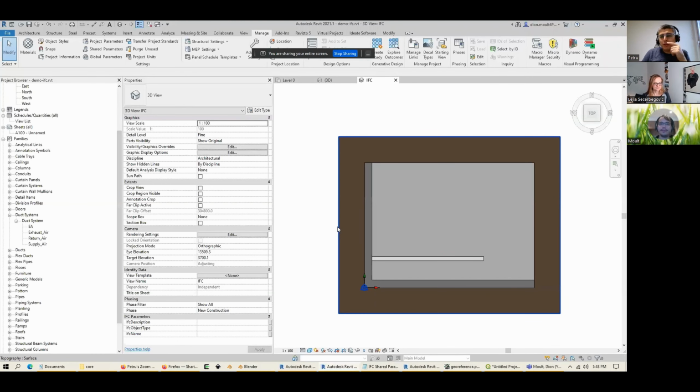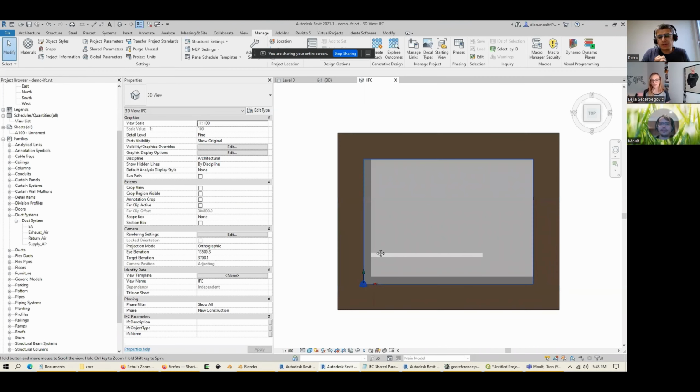But at the same time, if I understand this correctly, what Leila said, we are going to get better exports to IFC 4.3 because there is more focus on that as well? Well, currently Revit supports IFC4. 4.3 is just currently being released and it's still not certified. So we will have IFC 4.3 support soon in Revit, but that one is more focused on the civil and the infrastructure.